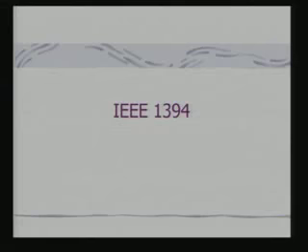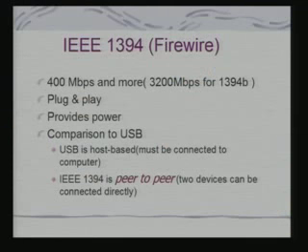Now, we shall look at another protocol which is IEEE 1394. This is again a serial protocol. It is targeted for high speed transfers, 400 Mbps and beyond, and in fact, this is what people are claiming as per the standard, which is 1394B standard.